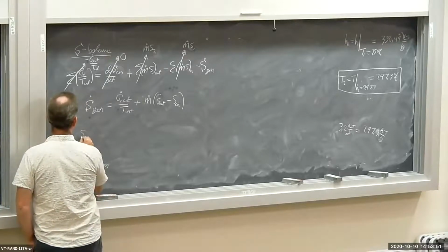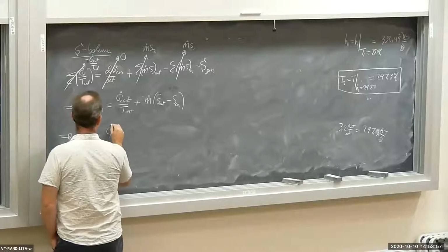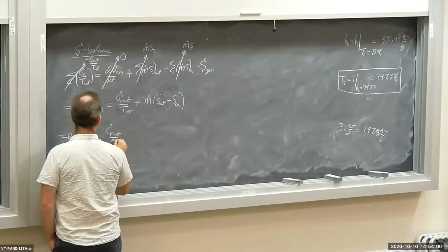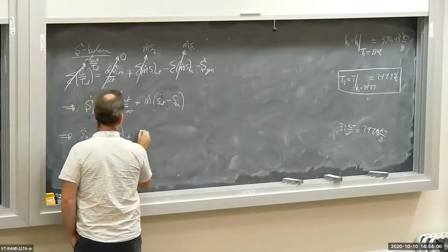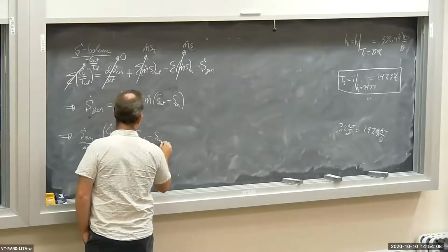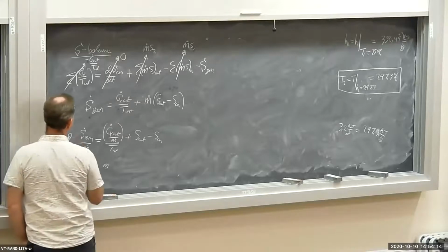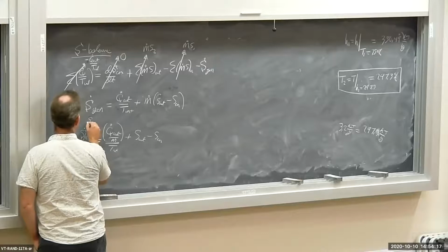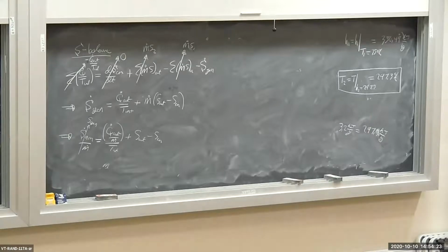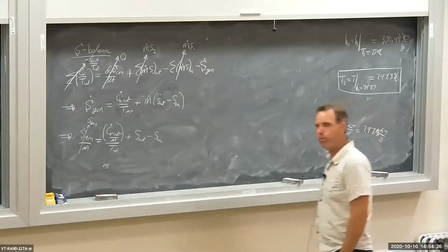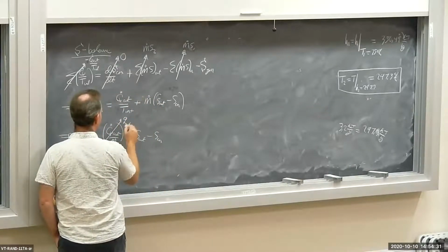So I've got S dot gen over M dot equals Q dot out over M dot, divided by the interaction temperature, plus S out minus S in. I'm dividing everything by M dot. The S dot gen divided by M dot is my lowercase s gen, or entropy generation per unit mass flow. And Q dot out over M dot is my heat transfer per unit mass flow, so this becomes my Q out.